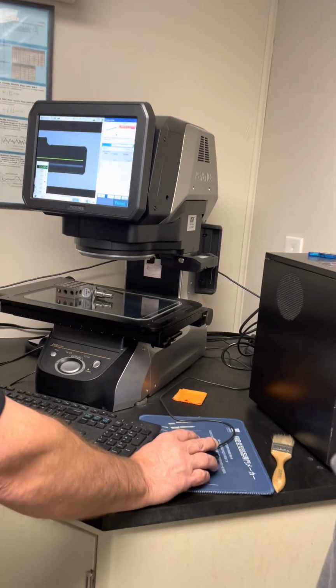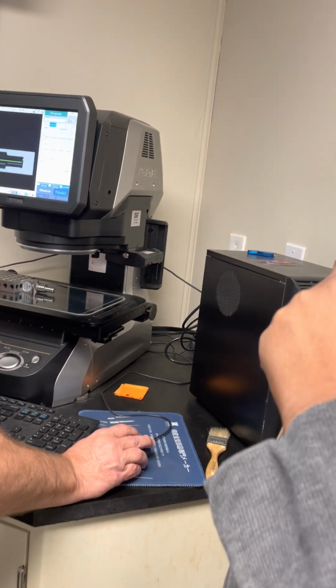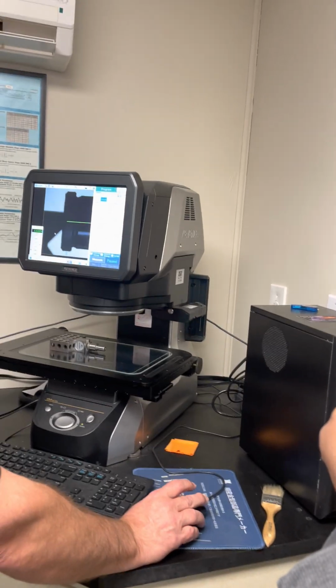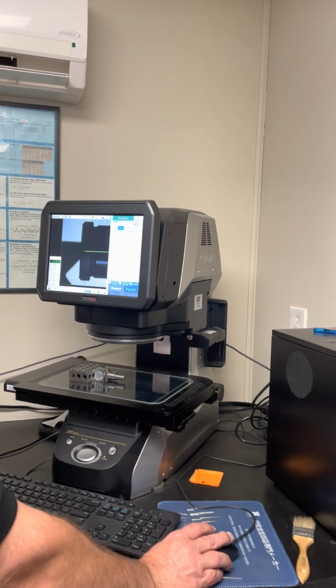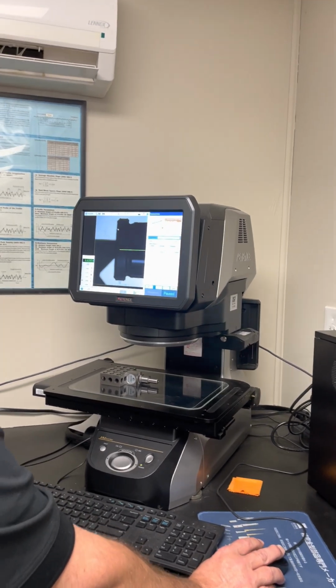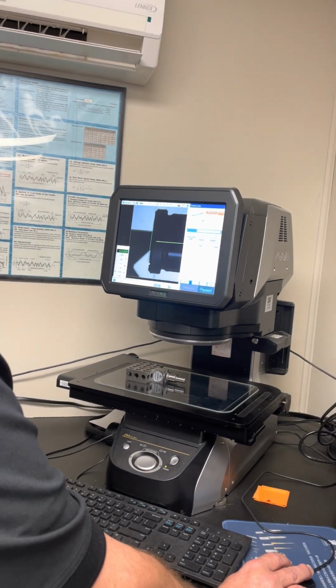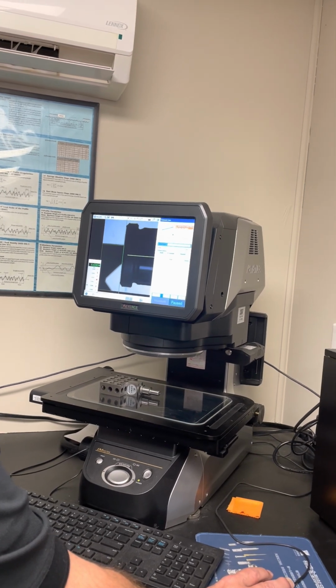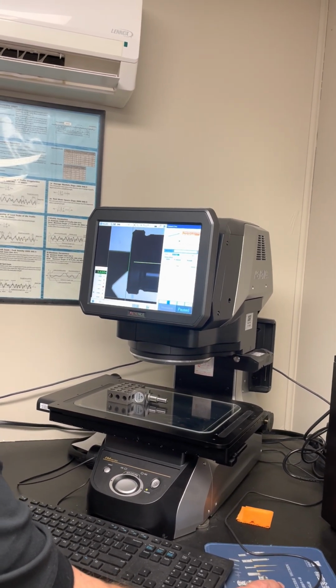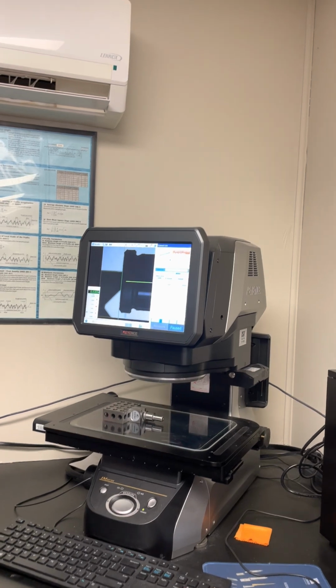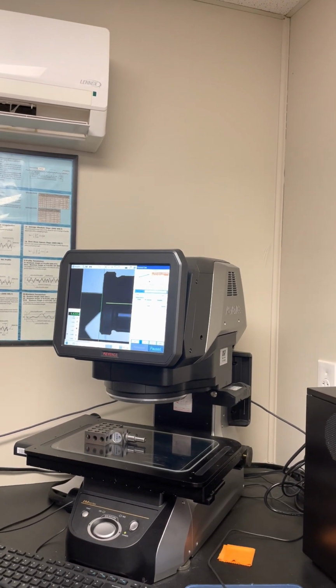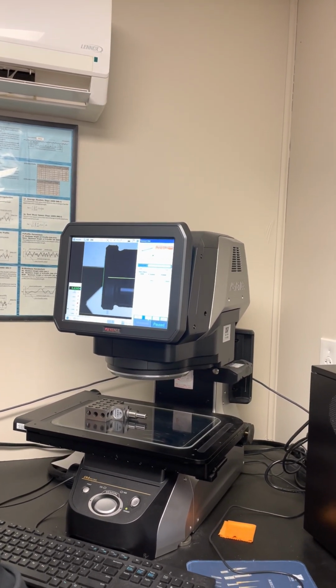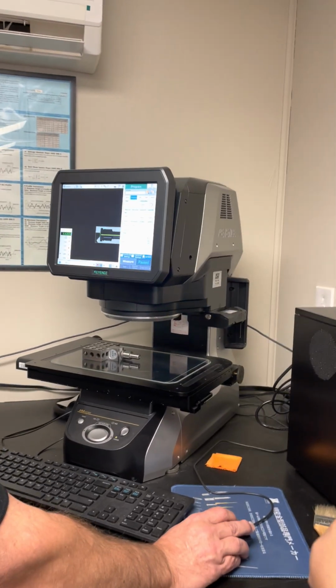I'll say okay, and let's do the back edge here. Again, I'm going to do it the same way. I'm going to go to connect lines, connect this line to this line, and let's just input the value. Let's say 0.5 this time, and there we go.